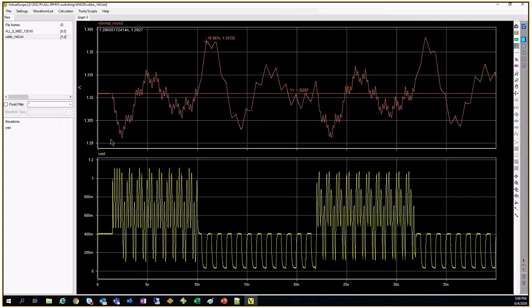So what he's basically telling is your peak to peak difference is there, right? That cannot be more than 80 millivolts. Okay. So if you see here, my peak to peak difference, right? From this is my lowest ever peak, and this is the highest ever peak over here. This should not go more than a given target.